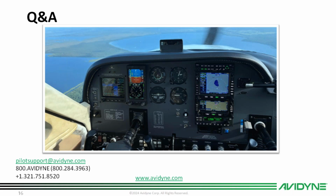So one of the requirements for a standby is, A, it has to be visible all the time, and B, it has to have an independent power source. So we don't meet those requirements to make it a legal standby. But like in this picture you see here, if you had an Aspen and then you've got a standby down in the bolster somewhere and they disagree, you can trust the 550 as the tiebreaker. You know that if the 550 and one of those agree, you can feel good about, okay, that's the proper attitude. You see what I mean? So it is an FAA approved TSO attitude sensor in that regard. Let's see what else we got here.